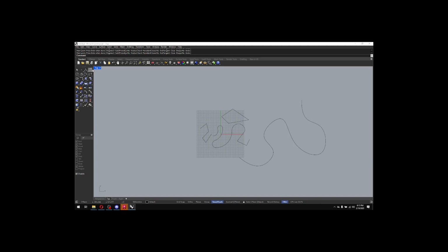The reason I don't like using the other version, which is the main one up here, that's called control point curve, is that it does this weird thing. I don't even know mathematically how it works, but that line's based off the location of these outside points, and you can adjust them. But for me, it's hard to visualize how that curve is working if my points are not along that curve. So I would always suggest doing the second one if you're going to use any splines.